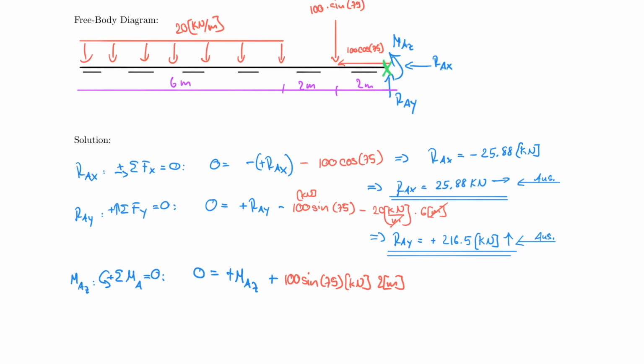All right. So now I can use my other force, which is also positive, 20 kilonewton per meter multiplied by 6 meters. And now comes the trick, which is not a trick really once you understand it, but you know that the lumped force acts here, so at 3 meters and 3 meters, and we need to take the sum of the moments about this point. Therefore, we need 3 meters plus 2 meters plus 2 meters. So let's write it down as such.